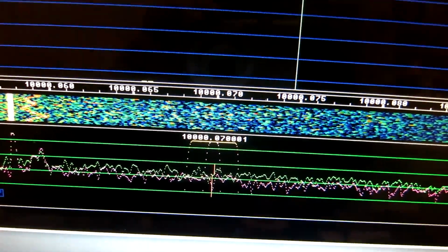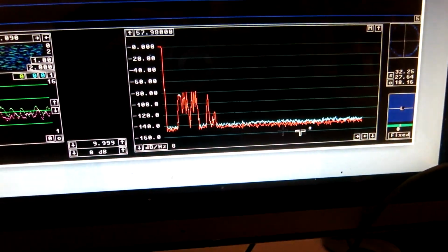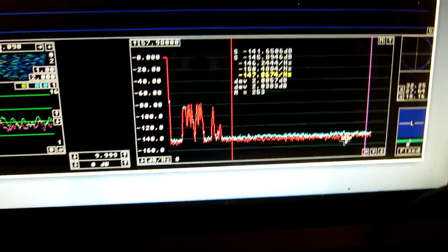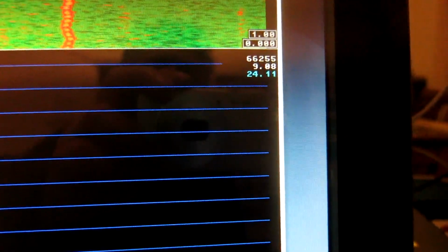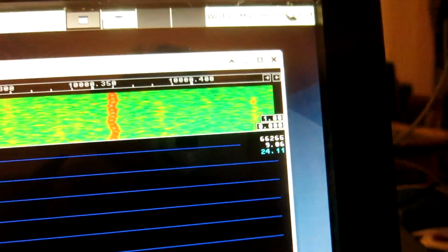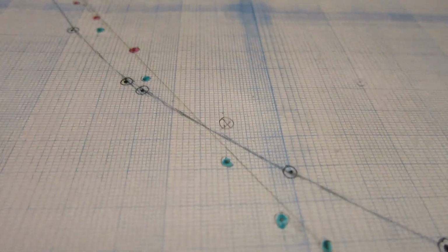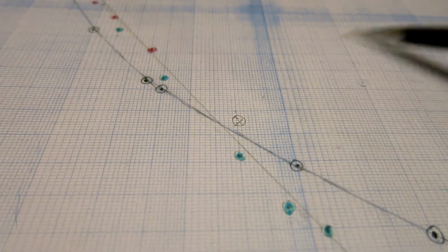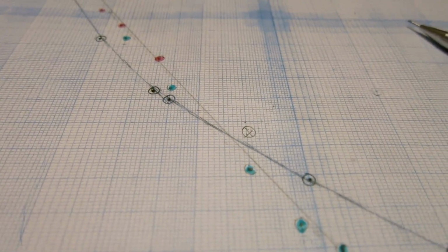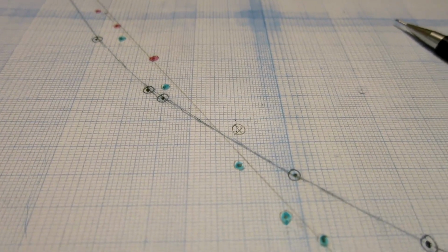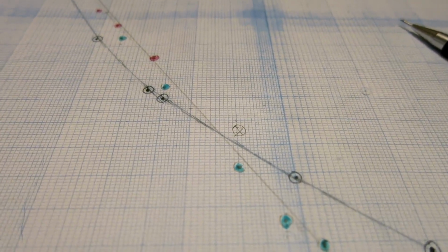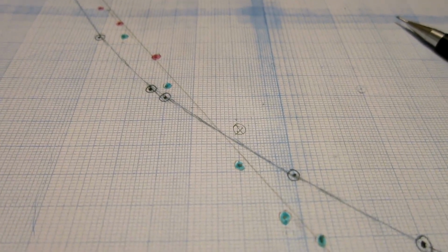I'm looking now at an offset of 70 Hz. And I evaluate the noise here. 147.9, and with correlation advantage 9.1. That is a point here. It is not better than before, rather not quite as good. So it seems this was not an improvement, rather the other way. I will evaluate more carefully to see